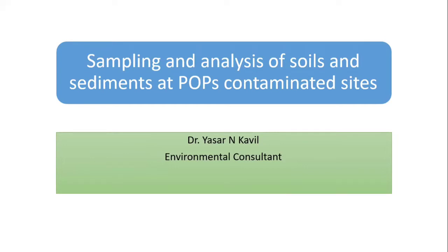After the inventory, we have to do the monitoring and assessment. Before we go for the monitoring, we have to do the proper sampling and analysis. So here I will talk about sampling and analysis of soils and sediment at POPs contaminated sites.